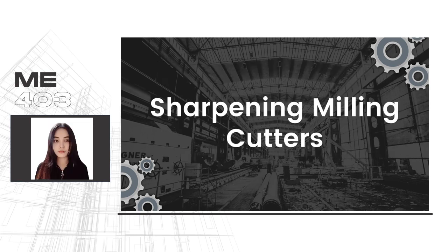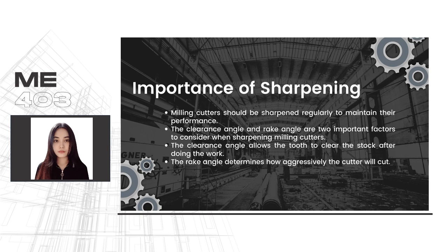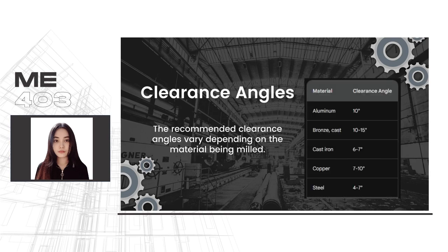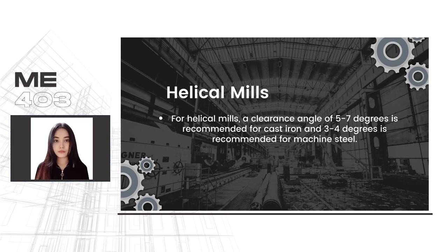Cutters must also be sharpened to attain satisfactory results. A dull cutter does not last long compared to a cutter in proper condition. Angles are taken into consideration as well as clearance angles of the cutters. Presented are the suggested clearance angles of cutters based from the Cincinnati Milacron Company.